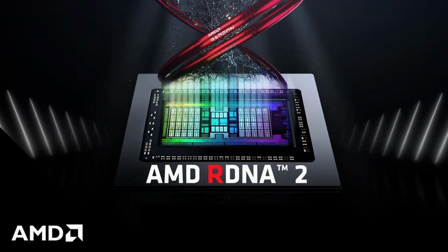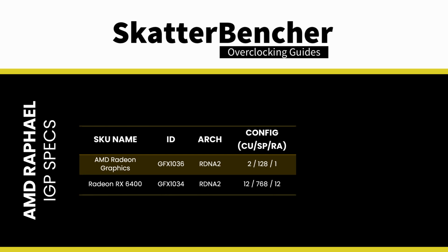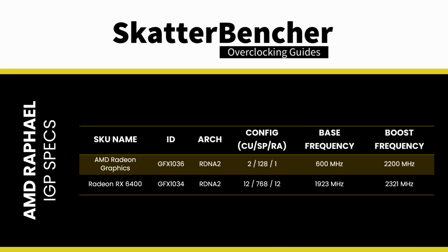It features the RDNA 2 architecture and is part of the Navi 2 product family. The integrated graphics has 2 compute units with 128 stream processors and 1 Ray accelerator. That makes it 6 times lower specification than the Radeon RX 6400. The base clock frequency is 600 MHz and the boost frequency under load is 2200 MHz.